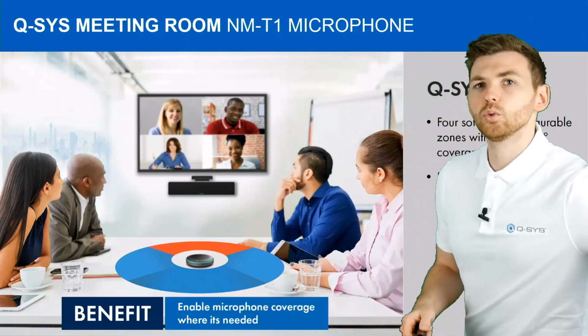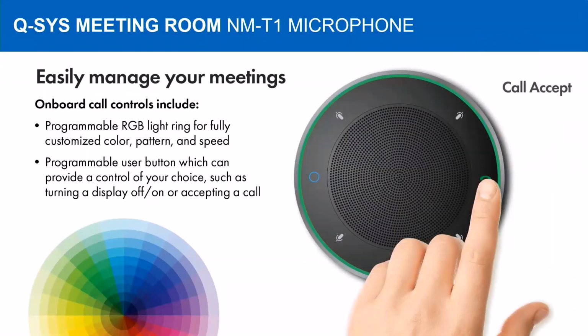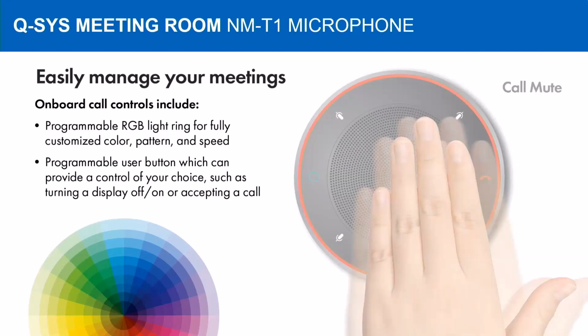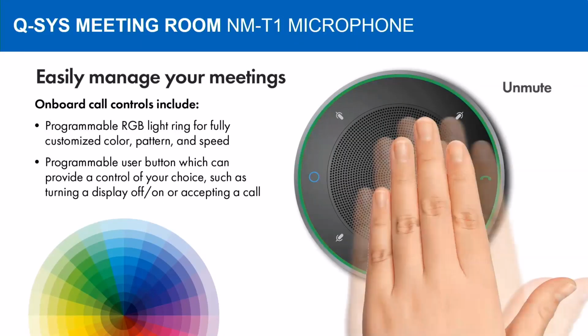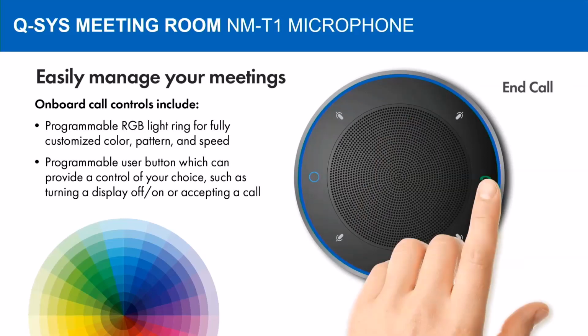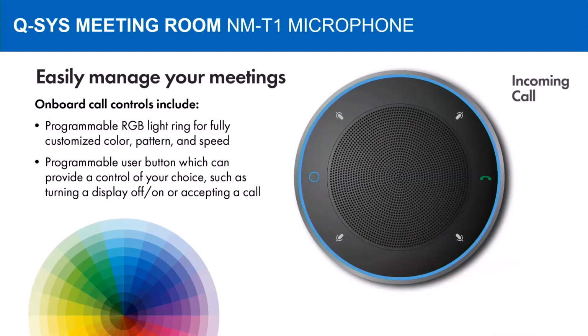But it also has quite a few neat little control integrations, so you can actually use this as a kind of control surface into Q-SYS for conferencing. So you see there we've got a call, hang up, answer button, so you can actually answer things like Teams calls, Zoom calls, phone calls on VoIP, BYOD as well. You can answer and hang up using that, via the USB connection that we're going to do. You've got, of course, mute control as well. You've also got a little blue button on the left there, which can be configured to do whatever you want. That's just a button that comes into Q-SYS that you can use as a trigger in the control engine.